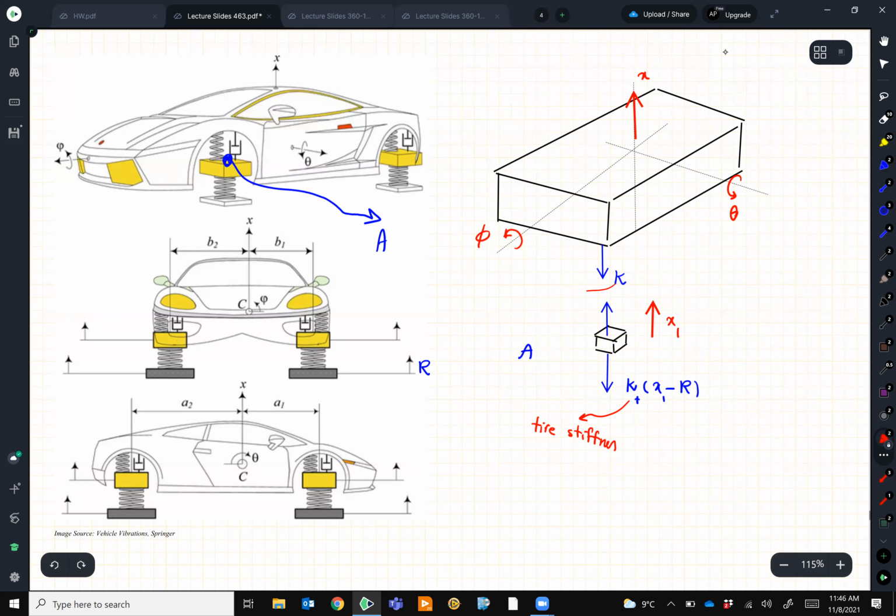And this K is the suspension or the chassis stiffness. Which again, check the internet, you can find some values or estimate them. It doesn't have to be accurate, but something reasonable. For example, do not choose K equal to 10 Newton per meter. That is small. So K here is what goes to the displacement of that thing.